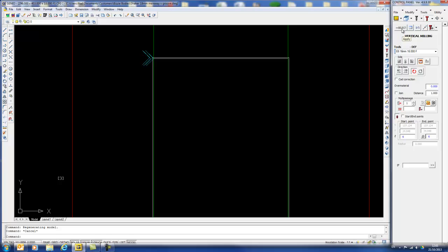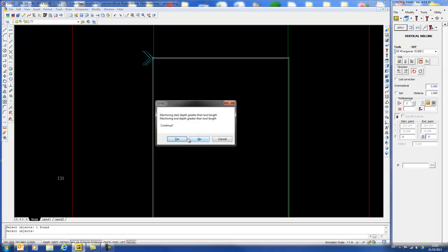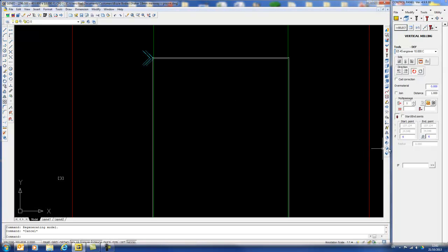Maybe you're using a conical tool or something. I don't know whether I've got one in there. Oh yeah, that's one there. So I'm going to go inside clockwise 6mm deep. I'm going to say select. I'm going to go on, let's say it's that line. I'm going too deep, so we'll stop that and let's pick a different depth. Let's go 4mm. That one.